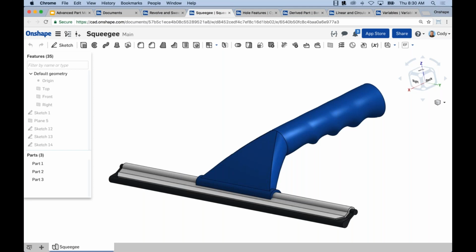like weldments, for example, pieces that are being welded together. I would definitely check out the beams feature script. There's also a wiring feature in the feature script library. So yes, you can use sweeps to accomplish this all yourself. Just sketch the profile, sweep it along the path. But there are also some commands that may speed up that process even more. I would look into the beams feature and the wiring feature.